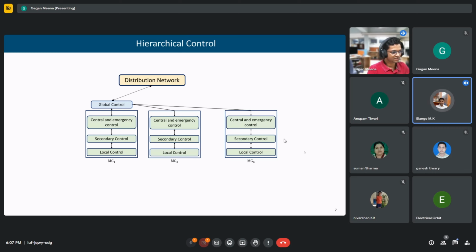Why not positive sequence current for calculating relay coordination under the category of adaptive control systems? They mean by relay coordination the backup protection. For backup protection, the negative sequence current has been used. That is why they have marked the answer as negative sequence. So for the adaptive control system, primary protection is not going to be considered? No, it is considered, but the question is for relay coordination. For relay coordination, the backup protection will come into the picture. For backup protection, negative sequence has been used. That is why the answer is negative sequence.